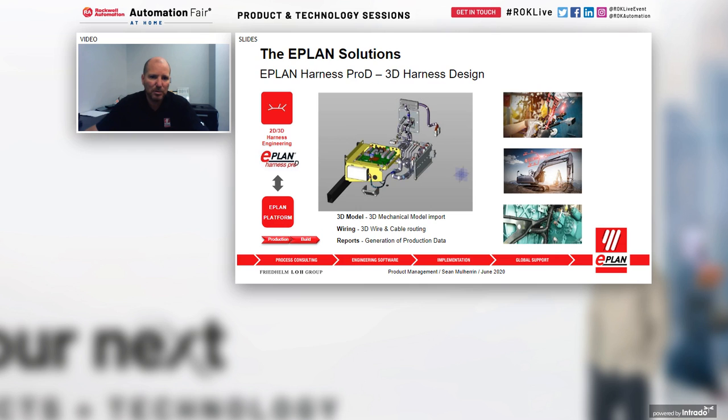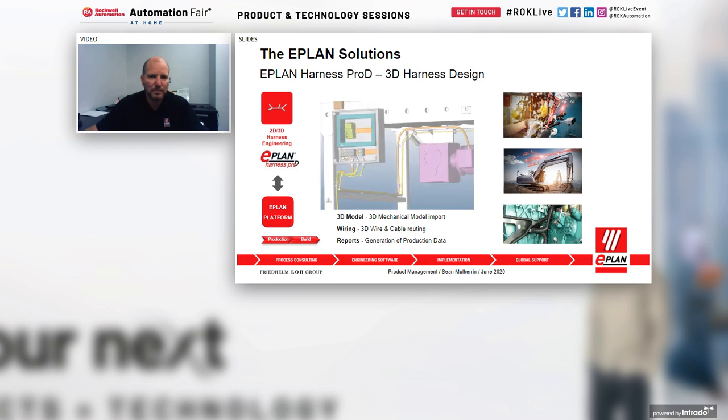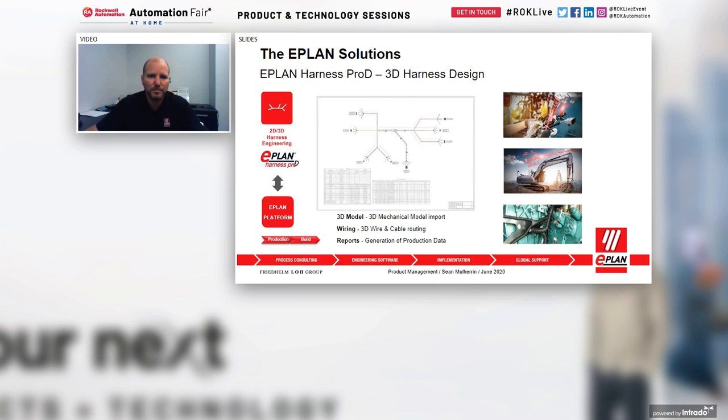So here's an example of a product, and then you can see the various different paths and the harness information associated to the control system. So that can all be laid out in Harness, and it can help you generate the manufacturing documentation for your harness a lot easier. Here's also a view for field cabling. So if you go from a machine, from the control cabinet all the way to your actuators that are on the machine, all the field devices, then you can also identify the routes around the machine that it can take, and the system can route the cables based on the schematic drawings that are available.